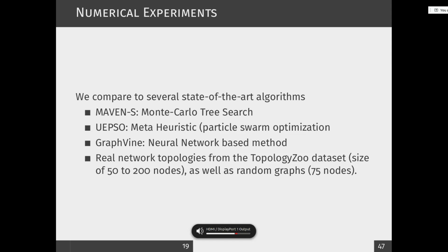So yeah, that's a perspective I'm interested in, the radio optimization part. For example, what if you know that your slice has some deterministic traffic, which in some 3GPP specifications you have, for example, for vehicles? Then if you have deterministic traffic, maybe your scheduler should be adapted to that. So it can do things better, because you can specify a different scheduler for each slice.